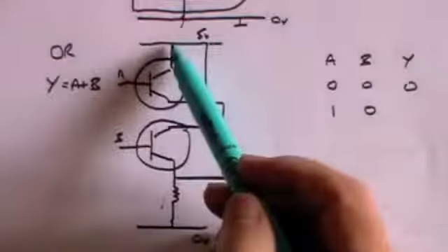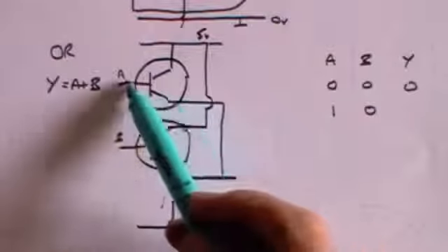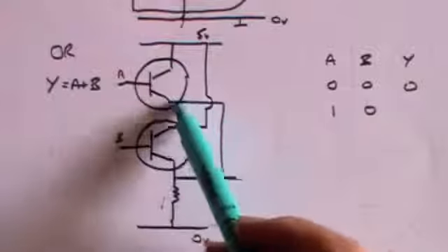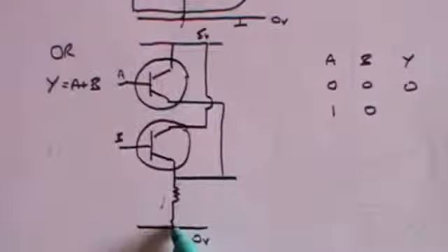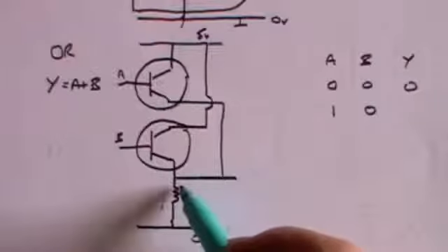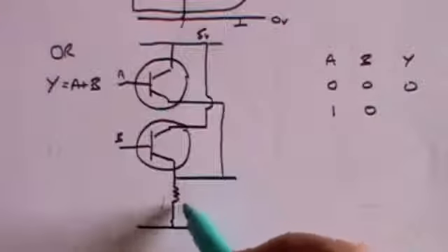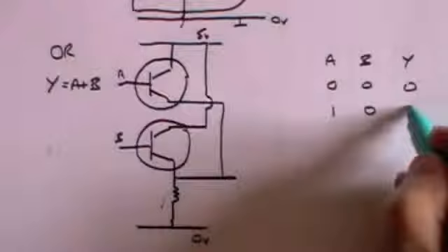I'll just show you the path again through that transistor, which is now closed. The switch is closed because there's a positive voltage here. So through the transistor, right the way down to the ground here. And that means that there will be a potential drop across the resistance, but there'll be a positive voltage on the output.